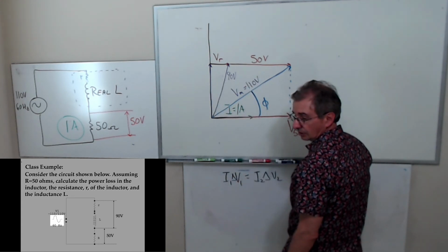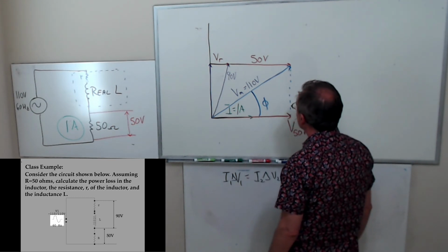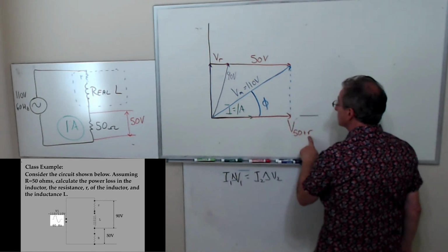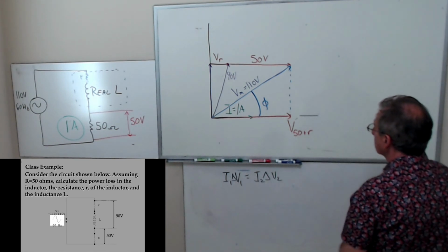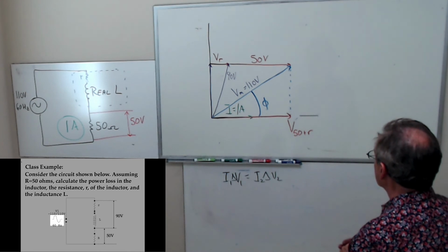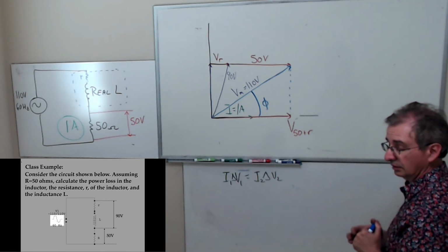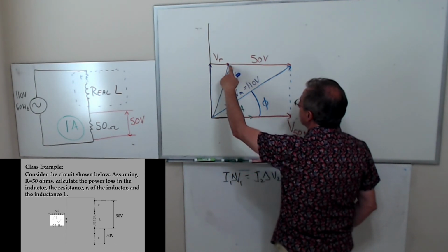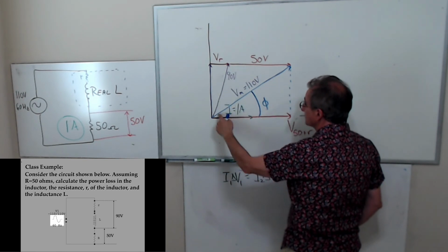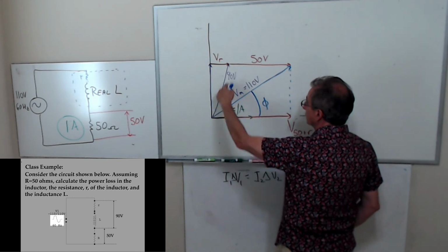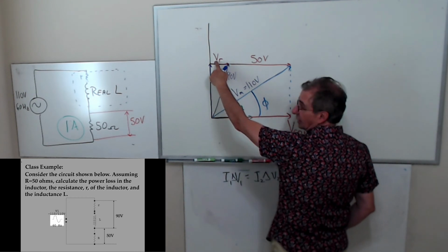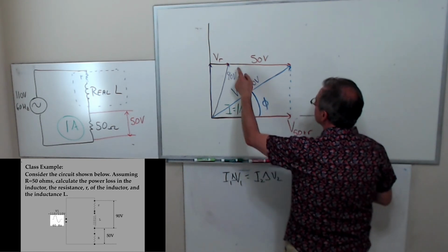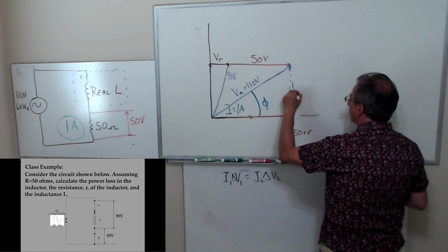This is the voltage across the real inductor, that's the voltage across the resistor. So what is that vector then, which is at the origin? The bottom horizontal one. This one? Yes. This is 50 plus R. And that is the voltage across the entire resistance of the circuit. Correct. But for V sub m, we take the vector for the inductor and the vector for only the actual resistor. Yeah, because this is both, right? Okay. Right. So this is the voltage across the inductor and this guy. And then you just got to add it to the 50 volts. Okay, that clears it. I didn't draw very straight, but that's supposed to be straight. But isn't this V sub L?